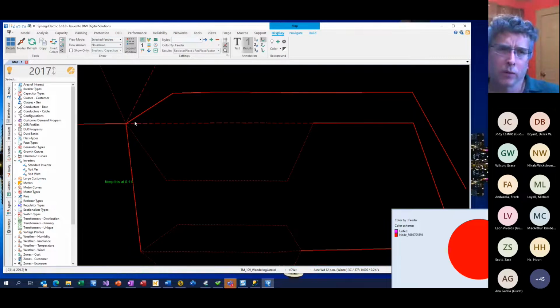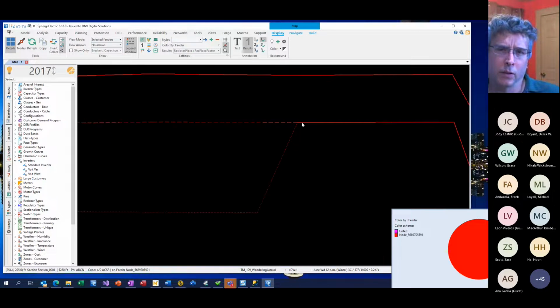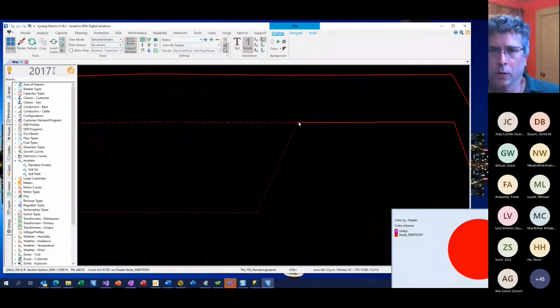Well, that's okay until we break apart. We can move sequence impedances along here, but when we come back together, it doesn't work. So we need to know what the impedance is at this point. What we would do, or what we still do, is run load flow and look at the change in voltage for a small change in current.